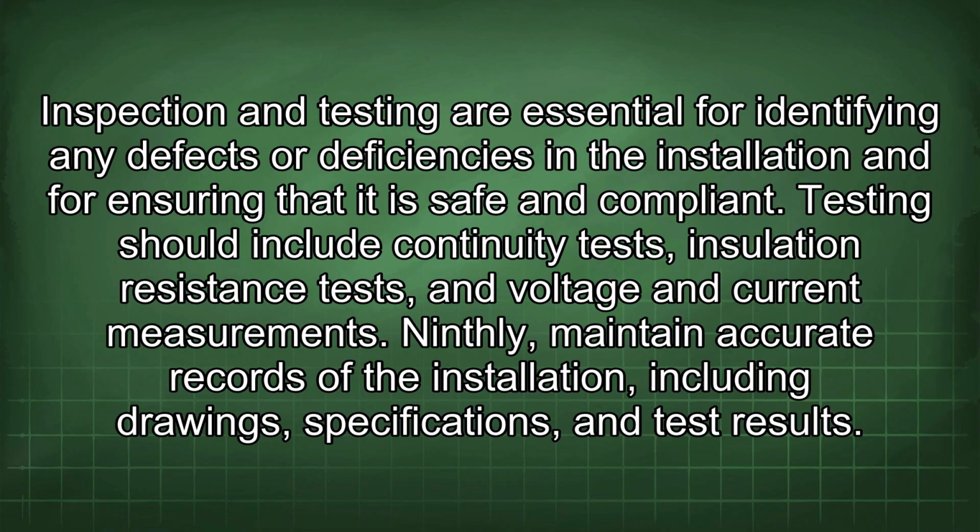Inspection and testing are essential for identifying any defects or deficiencies in the installation and for ensuring that it is safe and compliant. Testing should include continuity tests, insulation resistance tests, and voltage and current measurements. Ninthly, maintain accurate records of the installation, including drawings, specifications, and test results.